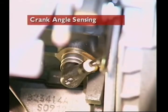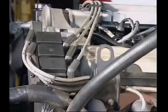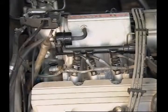This section examines crank angle sensing. Crank angle sensing uses information on the speed and position of the crankshaft to control ignition timing and injection sequencing. The control unit can then trigger the ignition and injection to suit operating conditions.